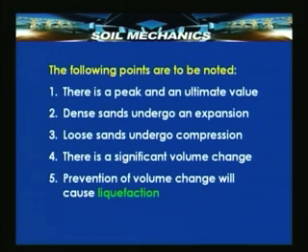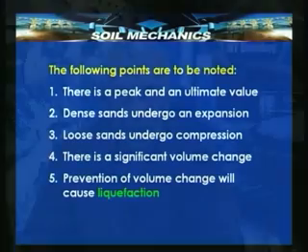Now, suppose we prevent this volume change. Then the shear stress that is responsible for causing this volume change will not be borne by the soil, and the soil will tend to behave like a liquid, and that is known as liquefaction. We also saw last time, having talked about liquefaction, what the critical void ratio is and how it can be used to decide whether a soil will liquefy under a given condition or not.